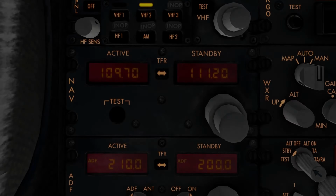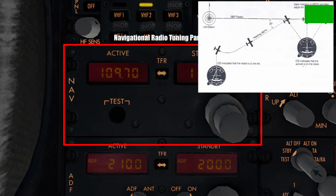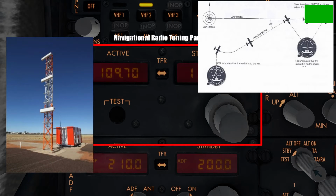Coming underneath, we have the Navigational Radio Tuning Panel, which is similar to the Communication Radio Tuning Panel, but instead allows pilots to tune in the navigational frequencies of certain VOR stations and other nav beacons on the ground to fly complex visual approaches, as well as to use the ILS or Instrument Landing System to align both horizontally and vertically with a runway for landing, as mentioned before.